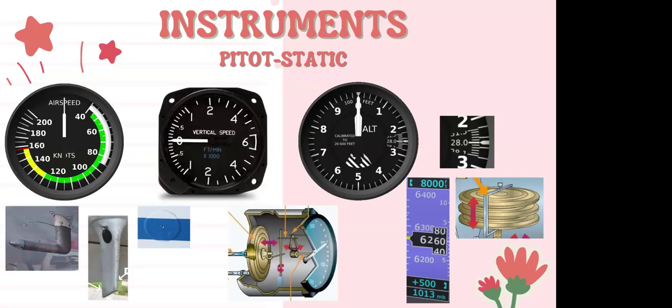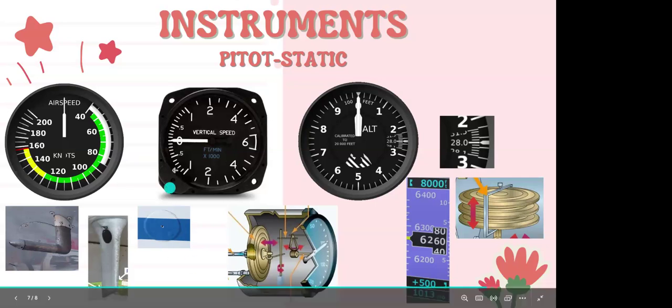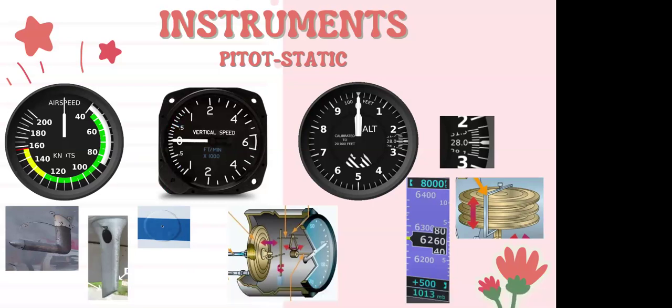It's built to have a calibrated leak, which means it's metering in that change in air so that you can cause that pressure differential and show that climb, right? So we're climbing, less dense air in the diaphragm, momentarily denser air in the case, shows, say, a 500-foot-per-minute climb.